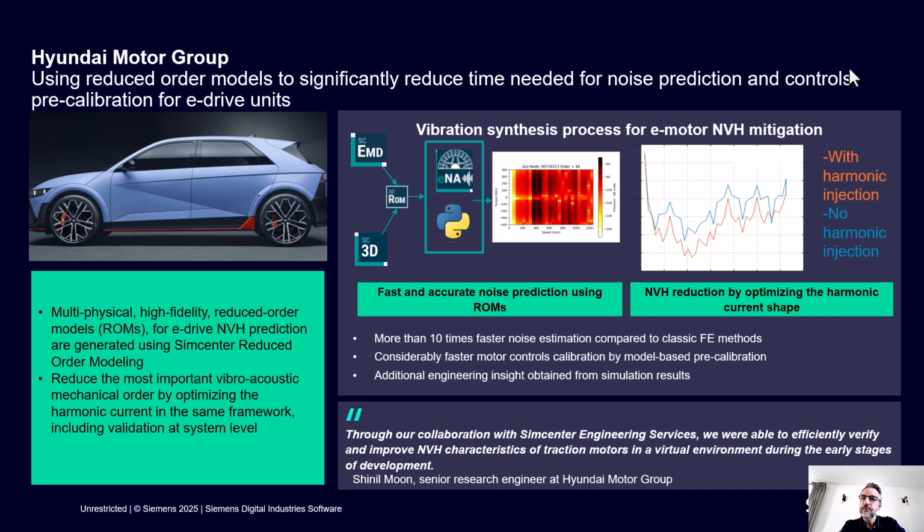Here we are injecting some harmonic in the input current in order to reduce the NVH response. So this strategy is evaluated by using the eNoise app in order to come up with a very fast prediction, so to really optimize the strategy.